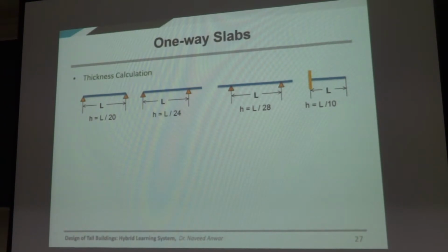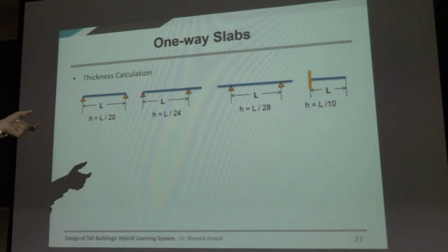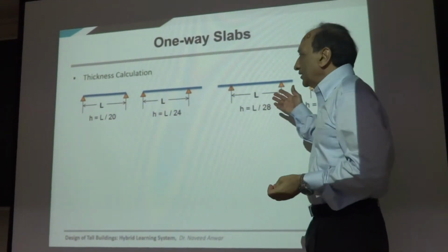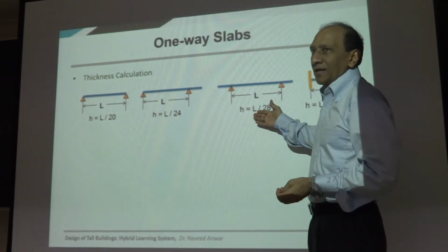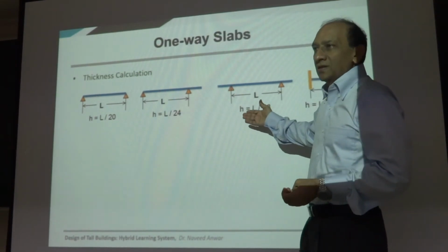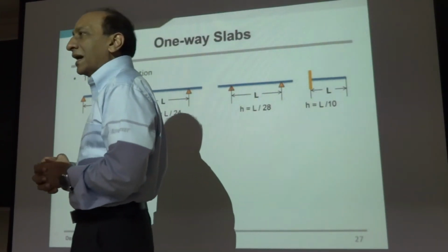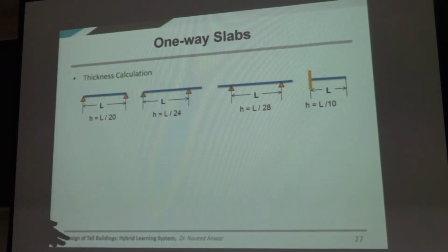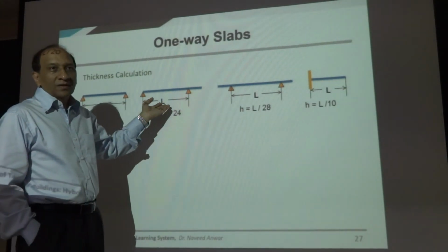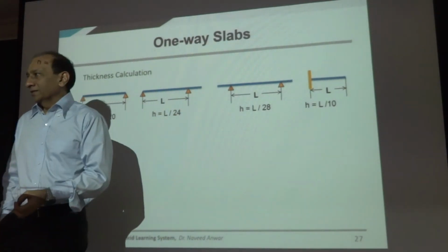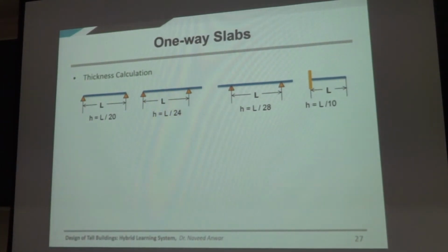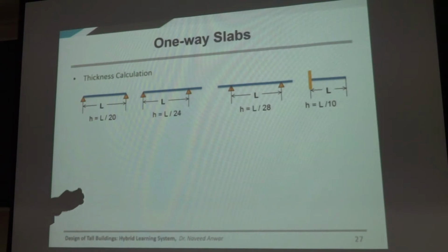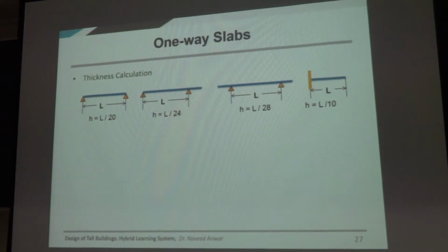Load. It doesn't care about the load. It is giving you the same depth of the beam whether I have very heavy loads or very small loads. So this deflection, this height estimation has no indication of the load level. I may be carrying very light loads, I may be carrying very heavy loads. So people may be misguided in using these calculations when they do not consider the loading. So this is important to understand that this is based on a typical loading in a building, average normal loading, nothing heavy, right?